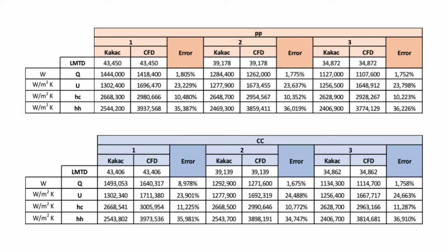On the other hand, CFD heat calculations give results that converge much more with each other and allow us to find the values of F, showing that this method tends to be much more precise, as would be expected. A comparison between heat flow and global transfer coefficients can be made, showing that for every case, values tended to be similar, yet noticeable differences were especially noted in the global heat transfer coefficient U, which depicts the most prominent error percentages.